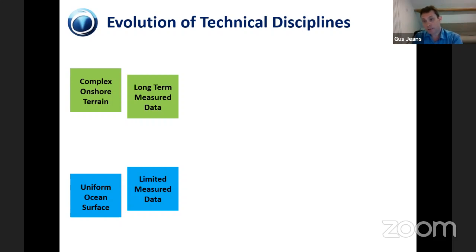Whereas in the offshore world, where the Metocean tradition evolved, there are generally much fewer long-term measured data sets in the offshore regime. And of course, the offshore winds are generally stronger and actually more preferable for generating wind energy. So you can't use onshore data and assume that it's representative of the offshore development region. There's generally much less measured data offshore, which means there's been, from a very early stage, a higher reliance upon numerical models for quantifying both extreme and normal winds.